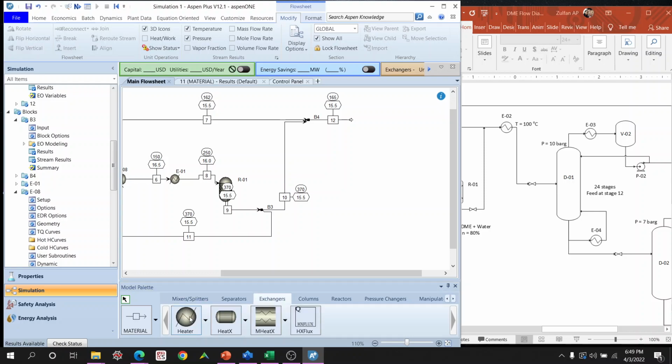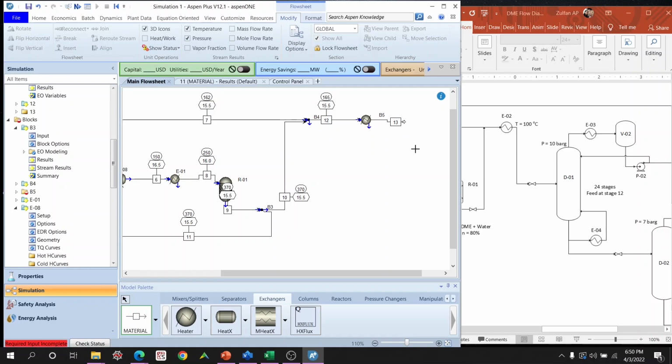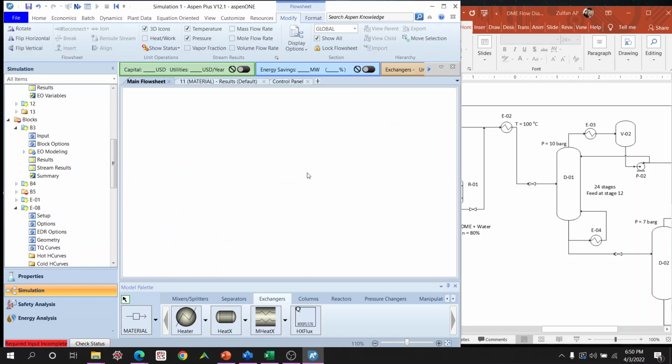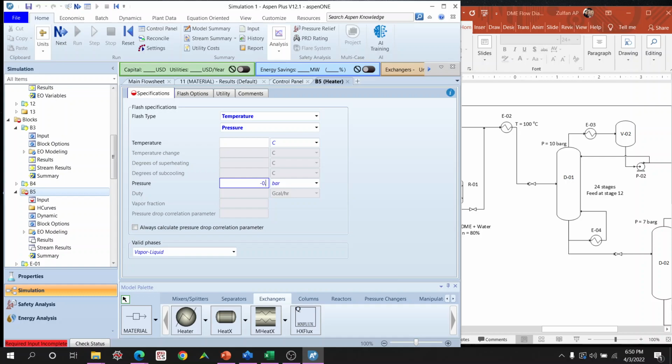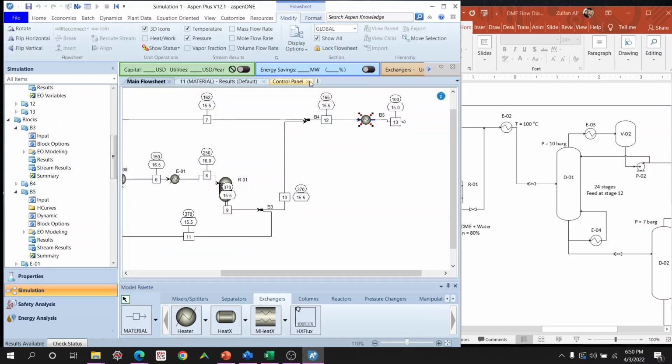So we have an exchanger with cooler, this heater or cooler, depending on the specifications that we are inputting into the unit. Connected, and then it has a certain pressure drop, obviously, a bar for example, and then the outlet temperature is about 100 degrees C. Run this, and you'll get what you want. Now we have 15 bar, 100 degrees C, and then we need to expand this via this valve.